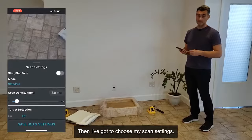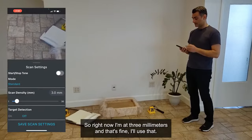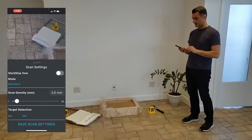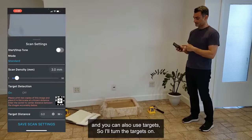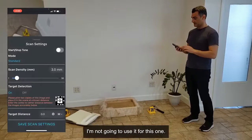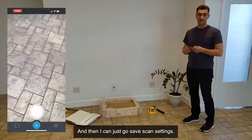Then I've got to choose my scan settings. So that's the second step. So right now I'm at 3 millimeters, and that's fine. I'll use that. There are different modes and tones and things like that. And you can also use targets. So I'll turn the targets on. You'll see that there's a target here that I can use. I'm not going to use it for this one. And then I can just go save scan settings.